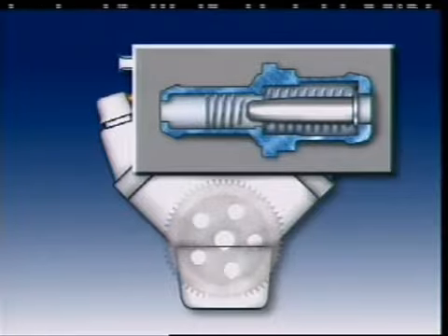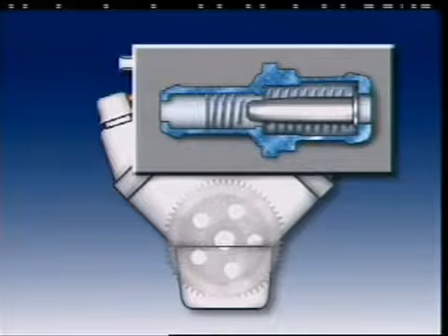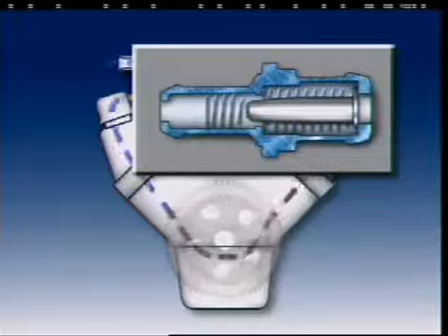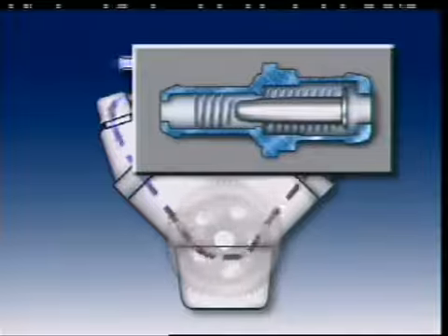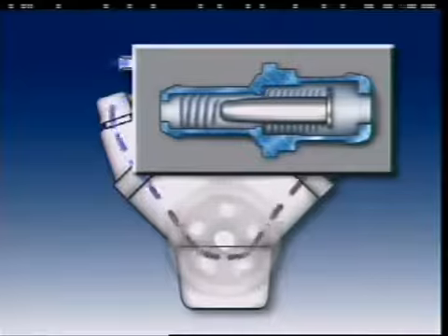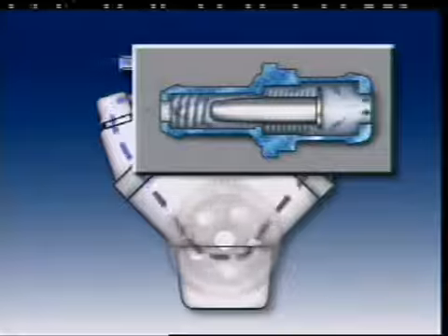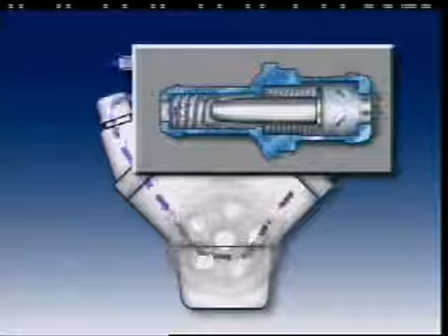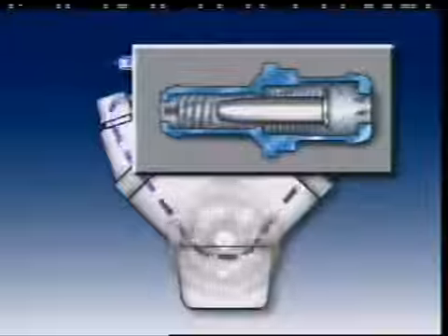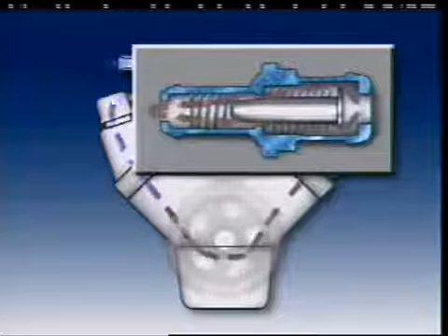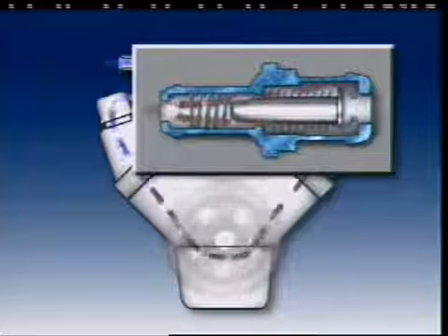With the engine off, the valve is closed and air cannot enter the inlet manifold. This allows the engine to start. At idle, low pressure in the manifold draws the valve to the other end of the body. This lets a small, measured amount of vapour pass the valve. At wider throttle openings, the valve plunger position allows maximum flow through the body, which gives maximum crankcase ventilation.